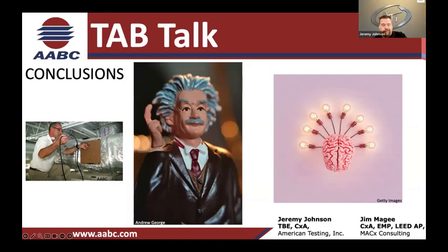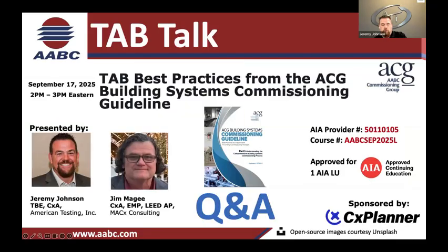You're doing it through a multitude of ways. I think understanding the flow and how the building is being built can be a huge factor with this too, and taking advantage of opportunities that you do have to test and balance certain parts of the building. With the controls contractor, does he have control of the valve? Does he not? How do we get valves open?